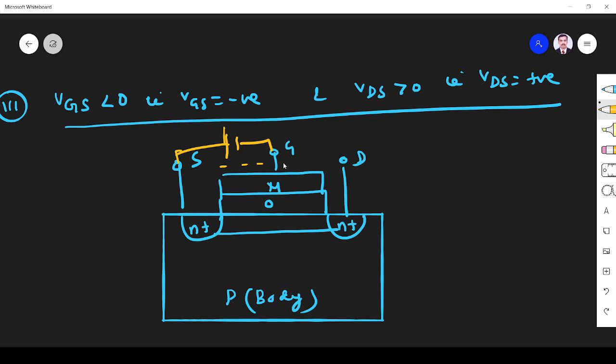The negative charge carriers accumulate at the gate terminal. Here you see this is the oxide layer, an insulator. Via this we will have an electric field. The electric field passes through the insulator, that we know. Since it is a negative charge, what will happen? We know the electric field will come towards the charge. That's what we have studied in the EMS course, right? So for a negative charge, electric field lines will be like this, acting in this direction.